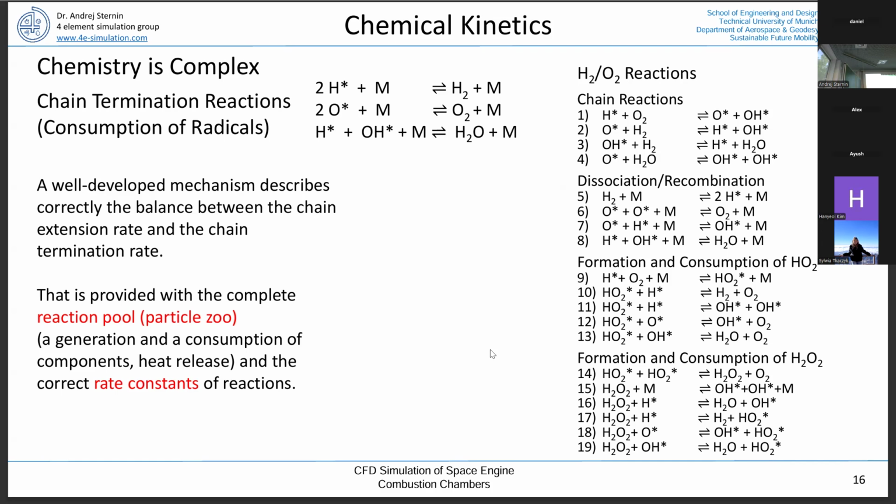At high temperatures, we may be able to split up hydrogen into a hydrogen molecule and an OH molecule. But if we reduce the temperature, we shift the chemical equilibrium and recombine those two radicals, meaning we are generating heat. So due to cooling, in the recombination reaction we are adding energy into the boundary layer.